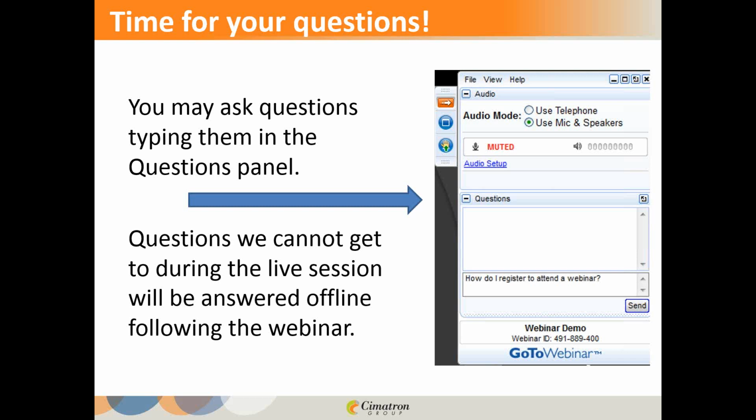Right. A couple guys asked kind of the same question. Can you account for process variables, forming speed, for example? Yeah, that's a good one. With a deep draw part, the slower you get, the easier the metal is to move. You're not likely to shear it so badly, that kind of thing. Right, and you're going to generate less heat. Right, less heat. That part of predictive intelligence, I would say we do not have. Okay. I can leave it at that. We can't do that yet.